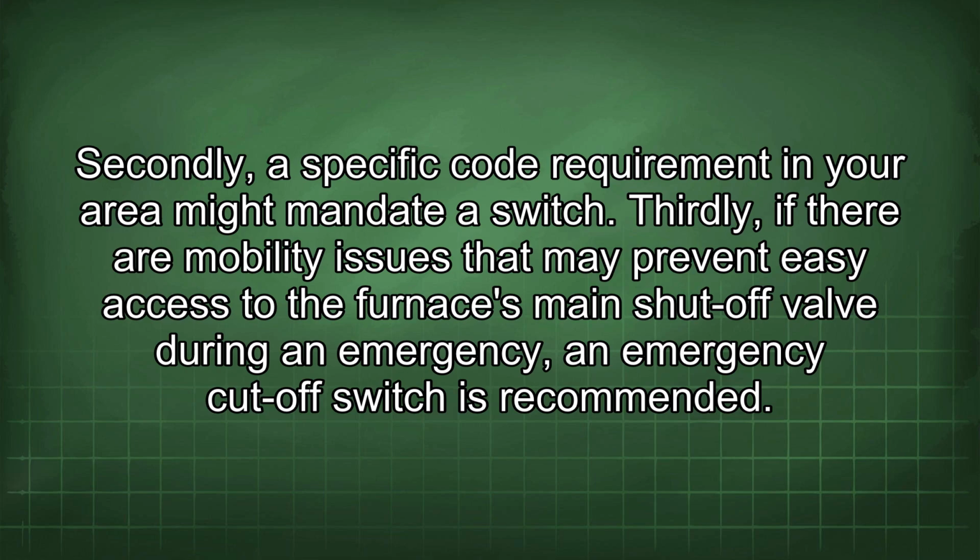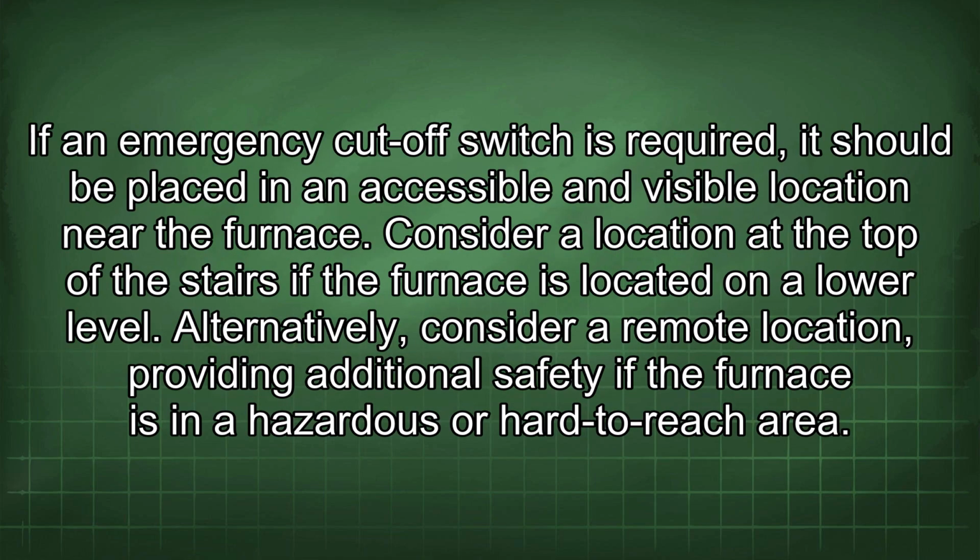Thirdly, if there are mobility issues that may prevent easy access to the furnace's main shut-off valve during an emergency, a cut-off switch is recommended. If an emergency cut-off switch is required, it should be placed in an accessible and visible location near the furnace. Consider a location at the top of the stairs if the furnace is located on a lower level. Alternatively, consider a remote location, providing additional safety if the furnace is in a hazardous or hard-to-reach area.